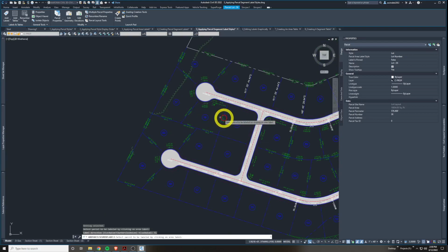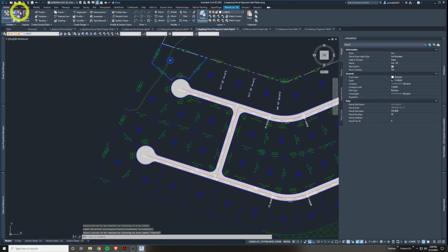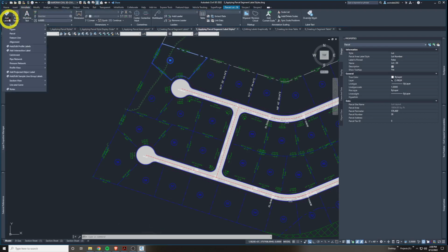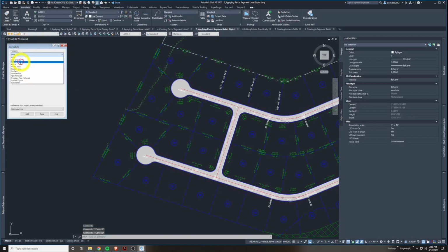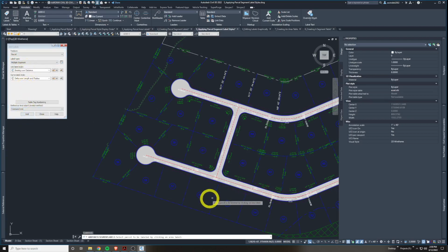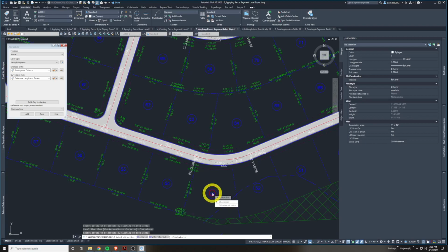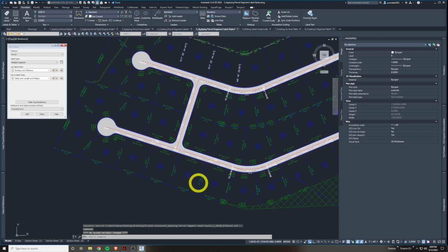So I'm just adding labels quickly this way. Enter, click that, enter. You can also do that going this method to home, annotate. I prefer this. Going back to your permanent dialog box, going to parcel, and you can say multiple segments. We'll just pick that as the land label style. We'll say add, pick each parcel one at a time, enter, one at a time, enter. I haven't figured out a way yet to do many parcels at once. That would be nice. There's probably a way somewhere in an add-in, but I haven't figured it out yet.